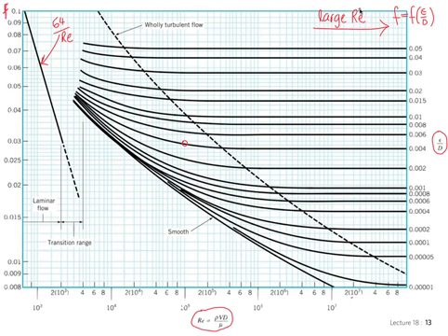And that makes sense because a very large Reynolds number means the boundary layer is very, very thin, and the friction is completely dominated by the roughness because the kinks of the surface completely penetrate the boundary layer. Question? So the friction force is almost constant if you have a large Reynolds number and surface roughness. So for all Reynolds numbers, if you have a large enough surface roughness, your friction force doesn't seem to change. Like your top line, this line doesn't seem to change very much.